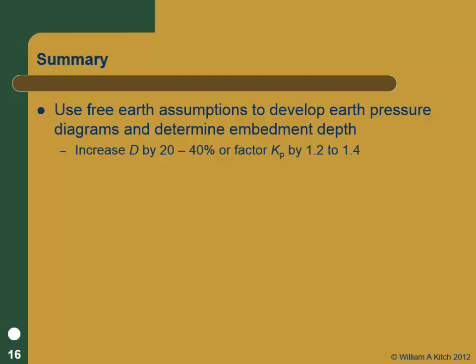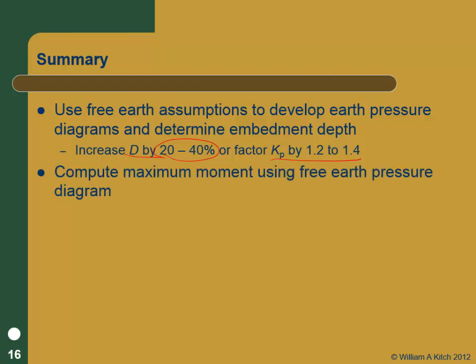I'm sorry, they're all static problems. It turns it into a determinate problem. We can calculate both our depth of embedment and the required anchorage force because it's now a statically determinate problem. We're going to increase D by 20 to 40%, or we're going to factor Kp going into it in the first place. That's how we're going to make sure that we have an appropriate system. We're then going to compute the maximum moment using that free earth pressure diagram. That's where it gets its name.